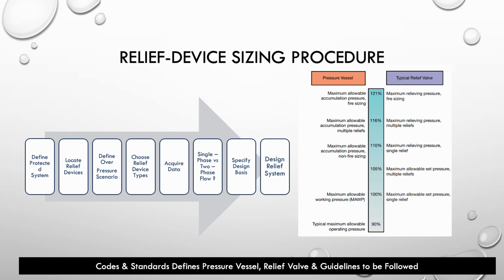So you can see it's not about the cost, it's all about what has been established in that industry while meeting the standards and codes that this industry must be following. You've got it. Again, like we mentioned earlier, a relief valve, at the end of the day, it's a valve. Yep. It obeys the same physical laws that we have talked about in a simple valve. It doesn't matter if it's opening to atmosphere or open to a vessel that's at 1 bar, for example, or 14.7 psia. Right.